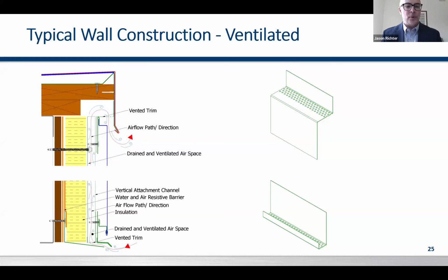So normally what you do is you pull back your blocking. You'll have to double up your coping cap blocking and create that space, pull your coping a slightly little bit off of the rain screen assembly to have that airspace, perforated Z at the top, again, for the moisture to weep out. And then you have what is considered an optimal design for your rain screen assembly here.